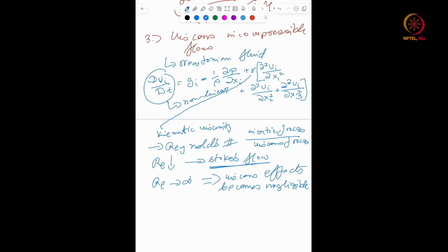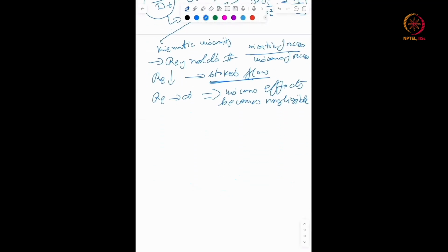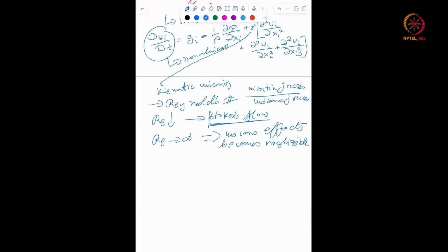However, this limit contradicts the physical fact that as Reynolds number increases, the flow becomes unstable and eventually turbulent. When you take a course on turbulence, you will see that you must consider friction, because that's where the cascade actually ends. So all these things you have to keep in mind. For low Reynolds number, you have Stokes flow, so the measurements become different.